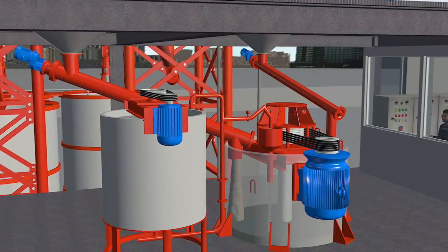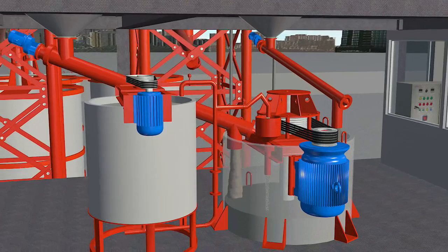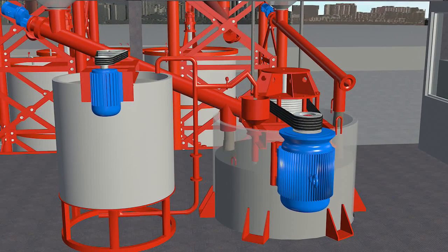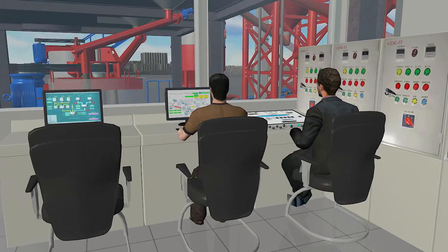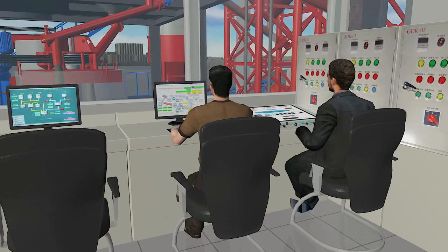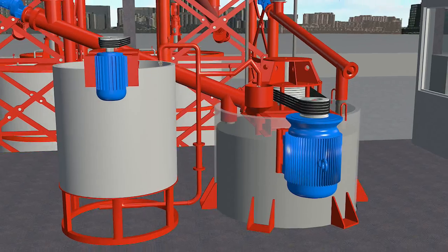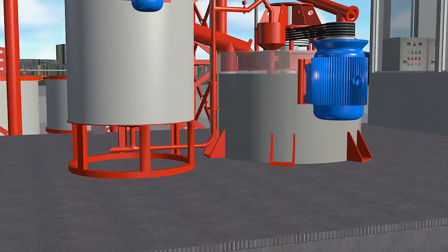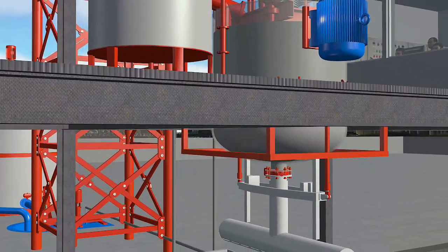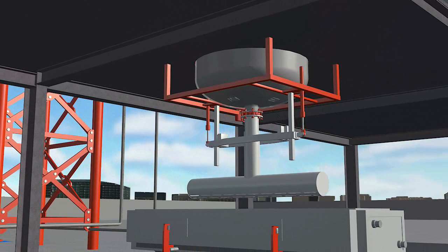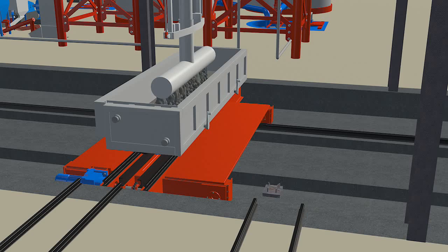After the preparation of the raw materials, the slurry, lime powder, cement, and aluminum powder or paste, which are respectively and precisely scaled, are discharged into the casting mixer with high-speed stirring. Then, the mixed slurry is poured into the mold for casting. The whole batching and casting system is controlled by a fully automatic control panel and computer to ensure the precise weighing and efficient mixing, which serve as the key point for QGM's AAC equipment to get high-quality products.